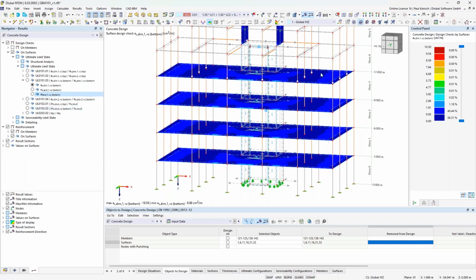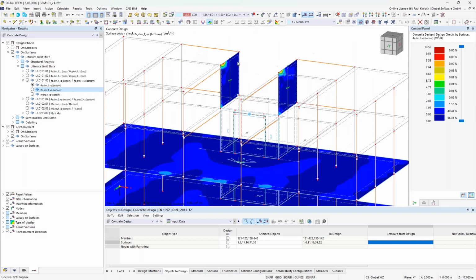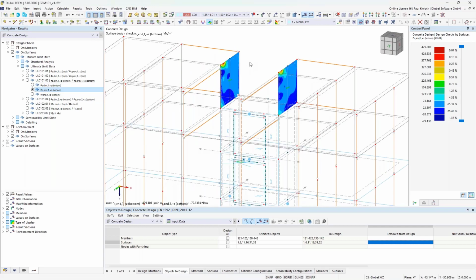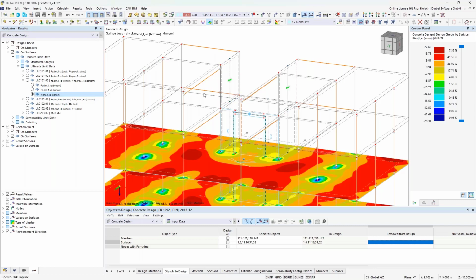So we now have, inside a 3D object or 3D structure, a separation between design membrane forces and design moments. For these regular walls here on this end, that's why I've randomly selected these two slabs here, we have these regular design membrane forces. So it's like you would design regular 3D objects. And this new setting here in the context of a 3D file is the design moment.